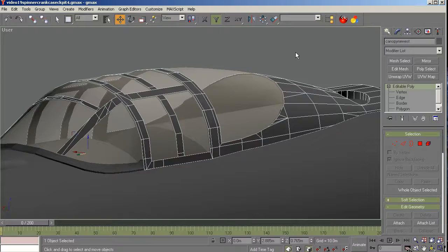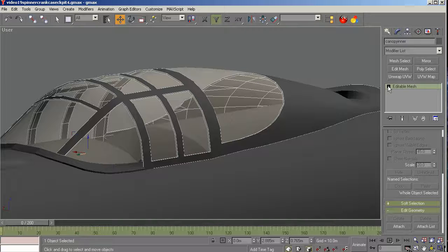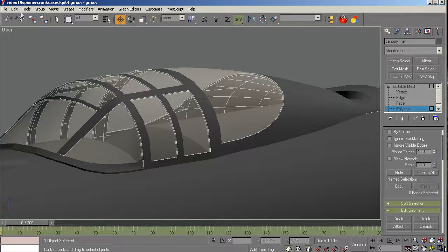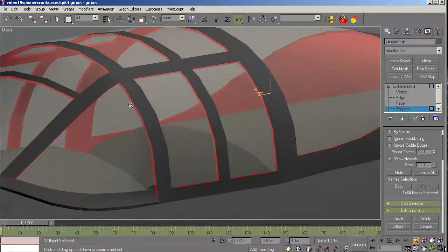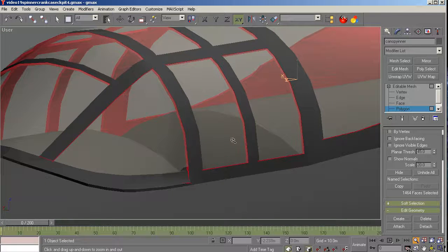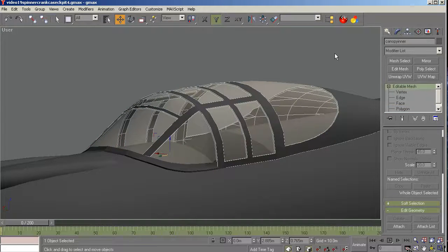I guess, yeah, I've got the exterior selected, but let's see if I can pick up, there it is. Editable mesh, selected all the polys and extruded them. I extruded them 3/8 of an inch, basically, about 0.0162 or something like that meters. And so I got a little thickness here around the interior walls, to give it a little bit of a more realistic look. So that's what I did there.